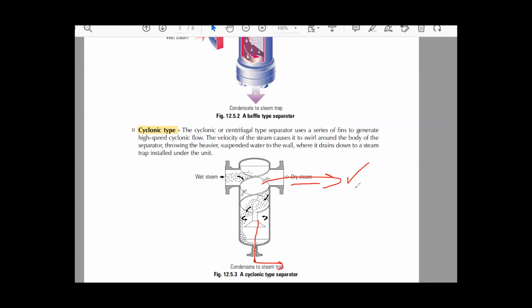But saturated steam is more and more efficient for heat transfer because hfg is higher. So it is more efficient for a plate heat exchanger, a calorifier, and to make a process of heat exchanging with another secondary fluid, to take this enthalpy and amount of heat and use it in a useful way, like warming a swimming pool.